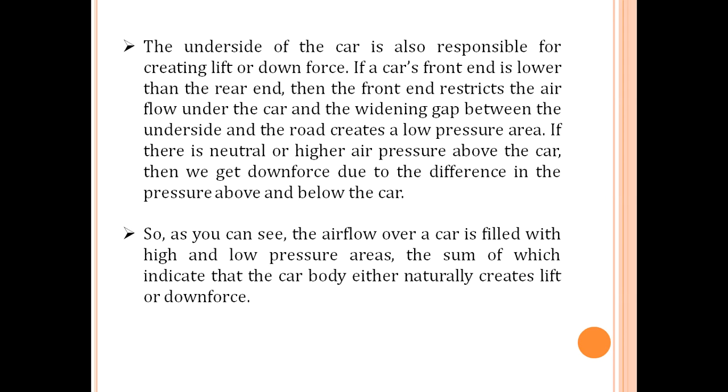So if there is neutral or higher air pressure above the car, then we get downforce due to the difference in the pressure above and below the car. As you can see in the next slide, the airflow over a car is filled with high and low pressure areas, the sum of which indicates whether the car body naturally creates a lift or downforce.